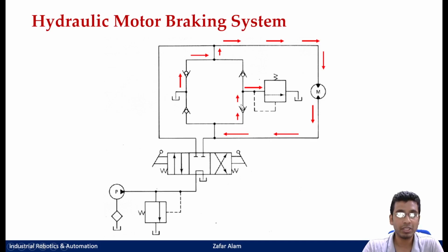Now this would come here, and this is just like your relief valve, that would start to build extra pressure, and once your pressure starts to build, this would open and your fluid would get drained out. So in this type of arrangement, your hydraulic motor would come to a halt gradually, till when? Because that much amount of load is required to keep this circuit in motion.